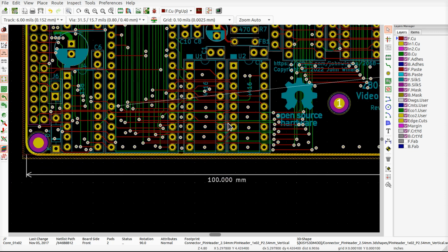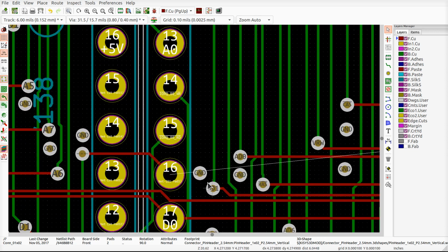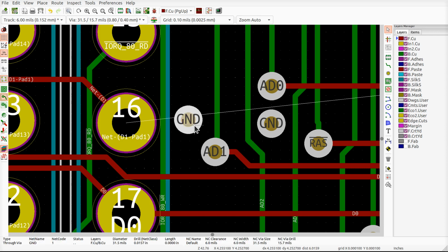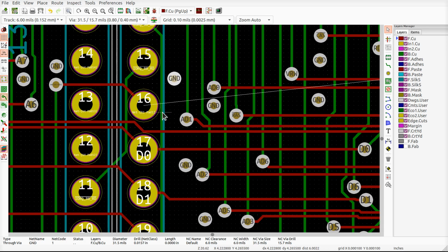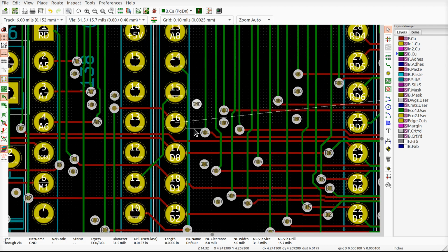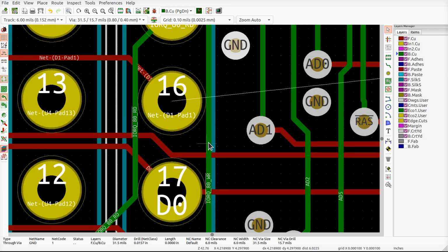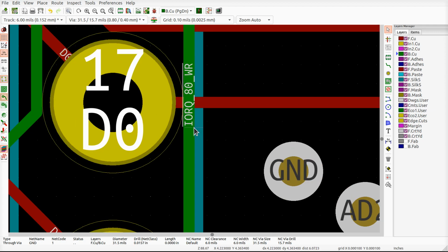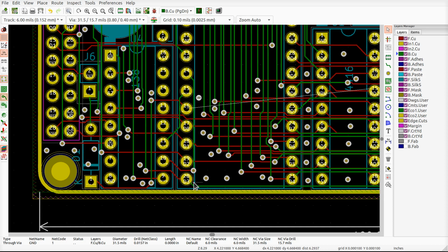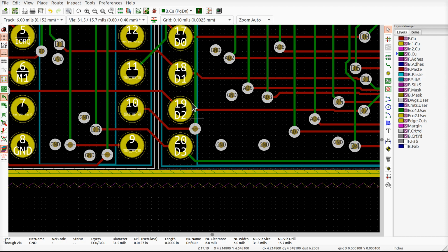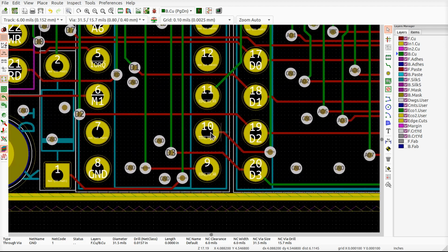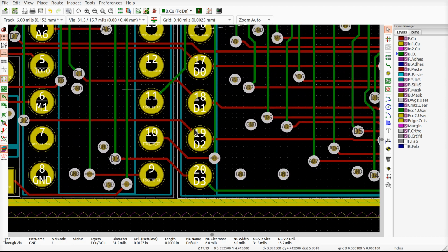Okay, dokie. What are we going to do? All right, we got a ground via right there in my way. You move it. Put it up there. Okay, look, all this extra room now. I'm going to go ahead and go to the back layer. And I'm going to just do the whole, oh, I got to get over this green guy here. What's that one? IORQ. What does that thing do? It comes down here and it pops through the board there to go over there. Oh, that's the output of the decoder, okay?